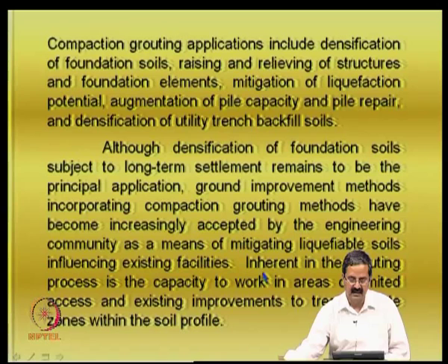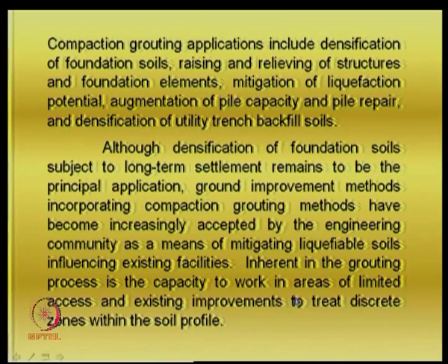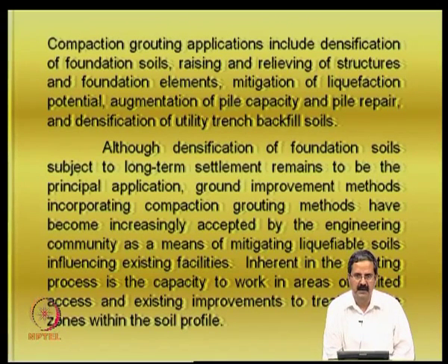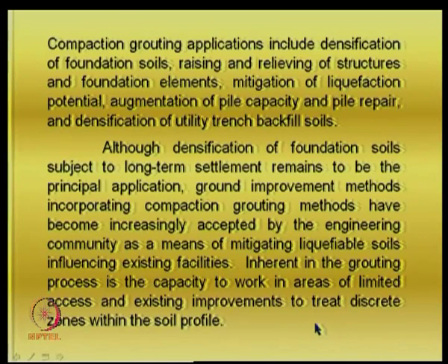Another advantage that is inherent in the grouting process is the capacity to work in areas of limited access. Say for example, there are some places where you do not have access to, like how do you construct a certain approach to do a certain repair job. So, when you want to do a repair job, an approach for that particular location is also quite important, and the advantage is that with grouting you can make corrections in places where there is limited access as well, which is a very useful advantage in many urban areas.